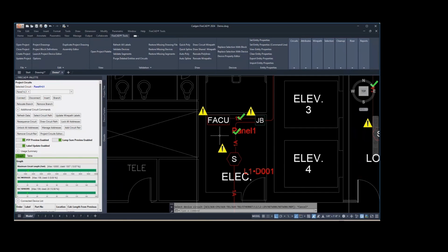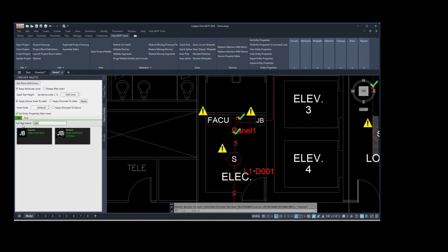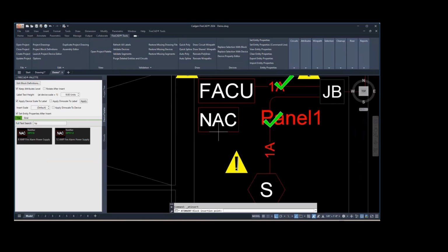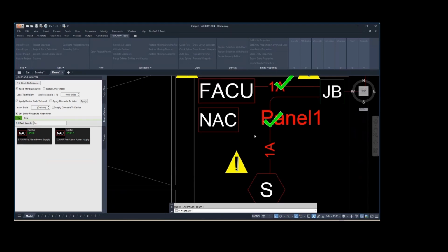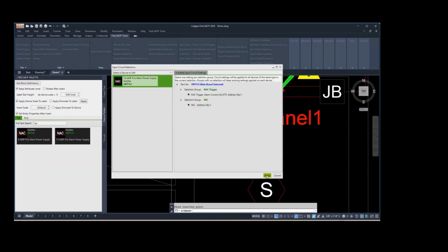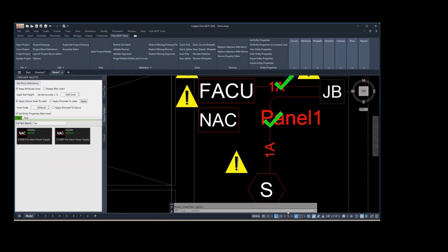Remote power supply. Okay, which part number would that be? HP something or other? Yeah, HPFF. 8 or 12? Let's go with the 12. I put a 12 there, and I'll put it right here. Now, I'm concerned eventually about wire paths between devices, and to avoid any need to have a short little stubby wire path, I'll just move this and snap it to the edge of the fire alarm panel.